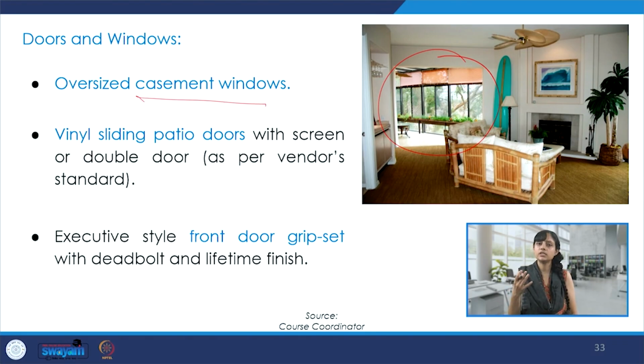So when we see interior design drawings and representation techniques, there we will probably discuss some of these. It is like, God is in the details. The drawings have to be really elaborate with each little detail, all inventories, all door window schedules, every kind of small to big detail has to be given along with the specification, material detail, dimension, everything. And like in the case of tiles, we will see whether it's a herringbone pattern or what is it. So all those things we have to put together when we are producing the interior architecture drawings.